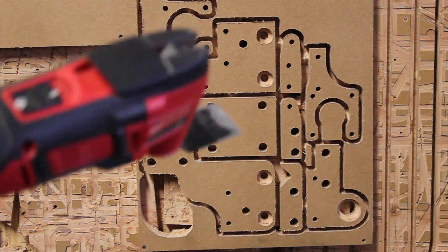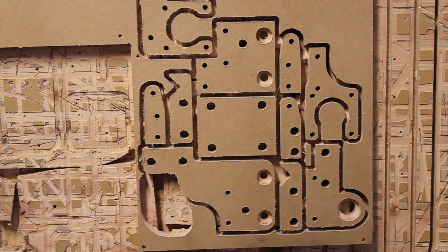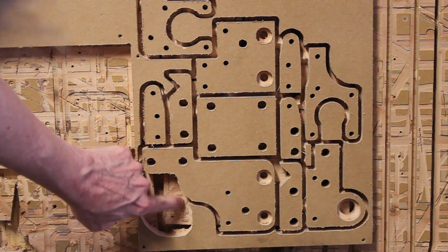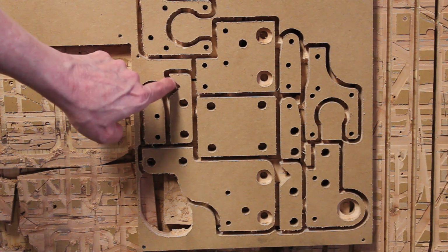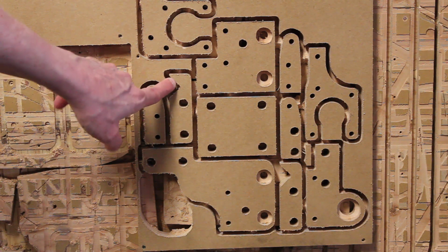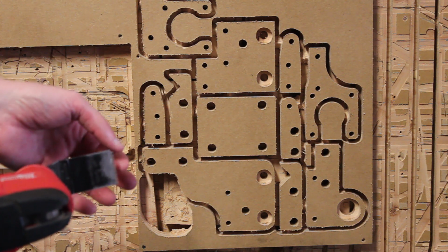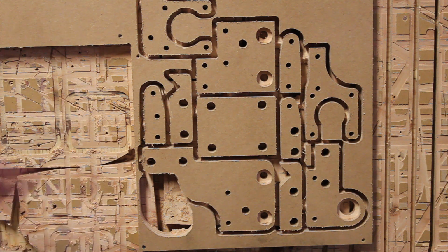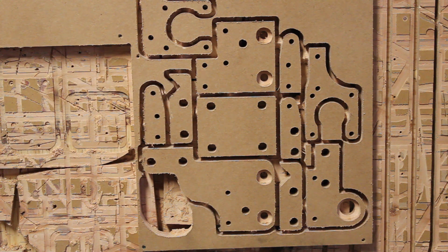There are some circles or curves that may be a little bit too tight, or certain areas like this one right around here was pretty tight. This one was pretty tight. If I had a holding tab inside here, that would have been almost impossible to do with this size of a blade. I would have to get a smaller blade, or do it from the other side. Maybe use another tool to get that out.